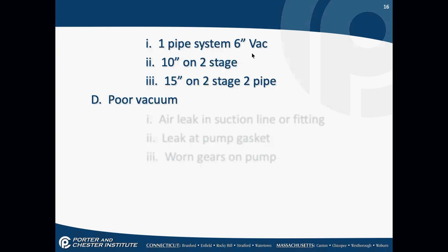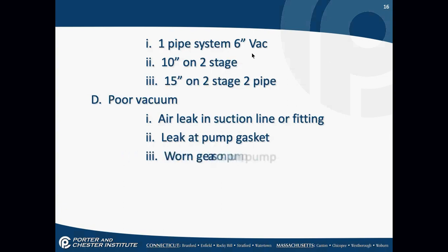If I don't have a vacuum, I have an air leak in a suction line fitting, or I have a leak at a pump gasket, it's still a leak. Or I have worn gears on a pump. All of these things have to do with poor vacuum.